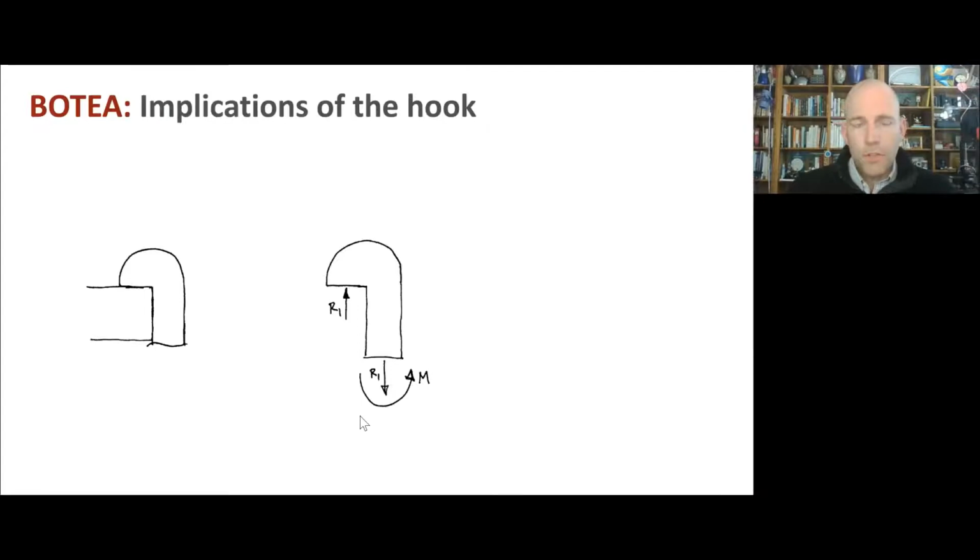They also tend to result in high stresses because you can think about it as this bit of material doesn't have as much of a mechanical advantage over the centroid as this other bit, and so it's at a disadvantage. So we know as a heuristic that we'd like to try to avoid bending moments, but because the table is here, we can't avoid it completely. We've already put things as close as possible to each other. So we're going to have some moment.